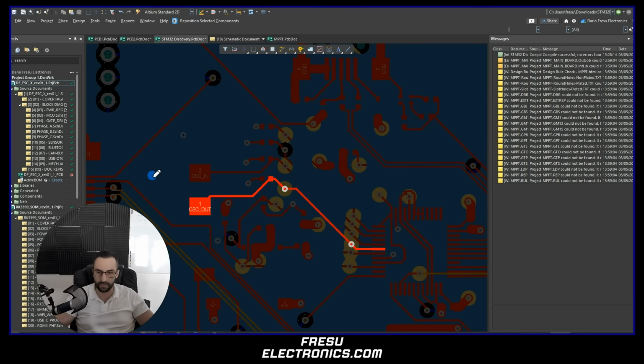So this is one of the most common issues. Why? Because usually what happens is that the clock signals are going close to the power traces. Then the clock signal couples with the power traces, and the power traces, of course, reach the power supply, and from the power supplies they conduct through the cables, and then the conducted emission test is going to be failed.